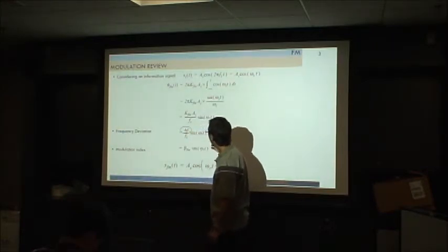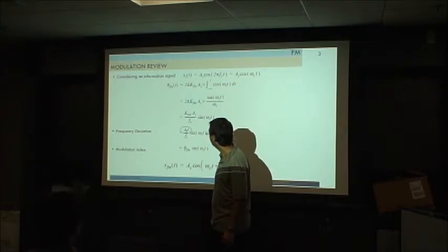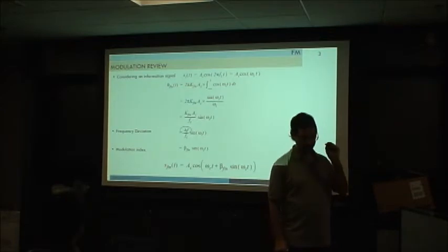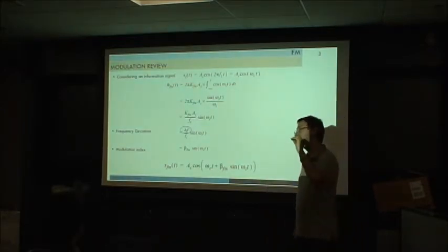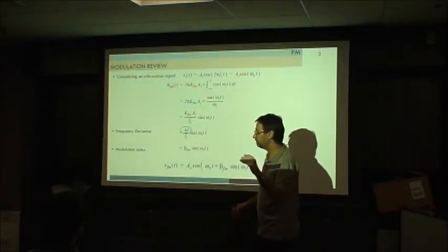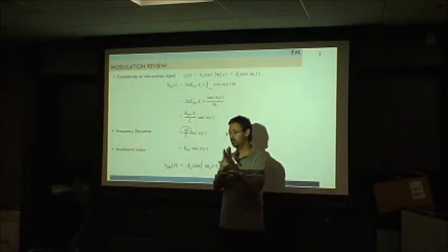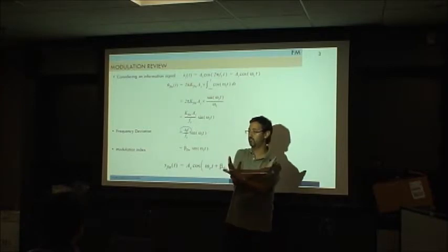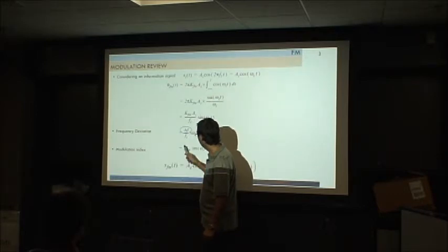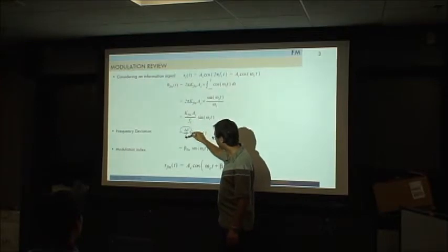Basically our modulated signal will have some delta F, which, if you remember, depending on that number, determines whether the frequency modulation is narrowband or wideband. That tells us how much I am allowing this modulation to move from my center frequency. This is delta F here, and this is the instantaneous frequency, so how much it changed from this one.